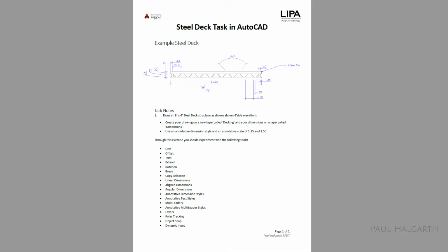The purpose of this task is to allow you to experiment further with basic drawing skills and measuring and using the modifying commands. So you're going to be drawing a steel deck, and we're going to be adding some annotative dimensions and putting them into 2 layers.